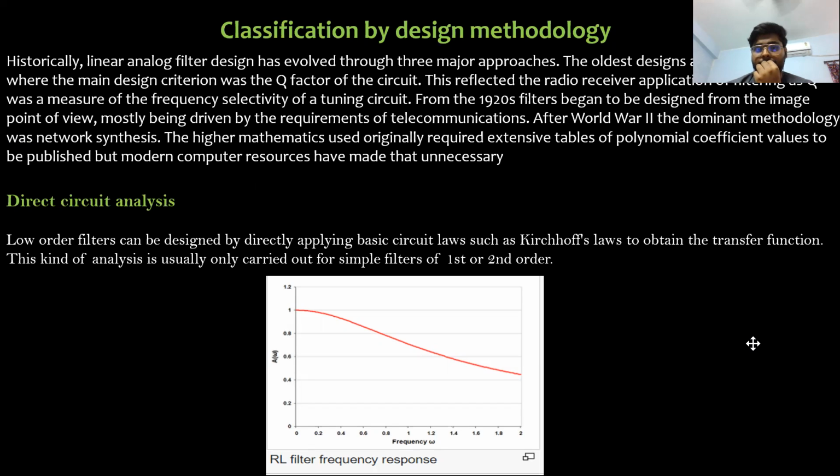The higher mathematics used originally required extensive tables of polynomial coefficient values to be published, but modern computer resources have made that unnecessary. Direct circuit analysis. Low order filters can be designed by directly applying basic circuit laws such as Kirchhoff's laws to obtain the transfer function. This kind of analysis is usually only carried out for simple filters of first order and second order. This is a graph for RL filter frequency response. We will move to the next slide.